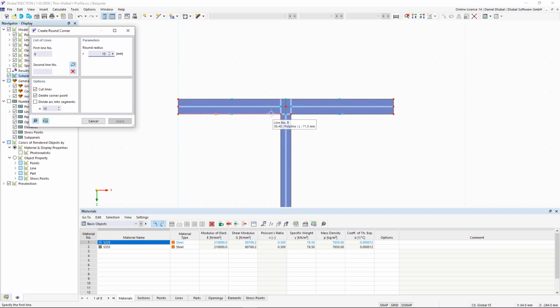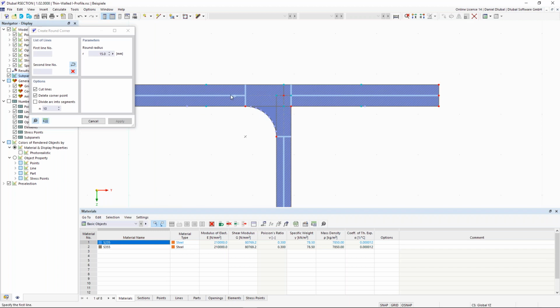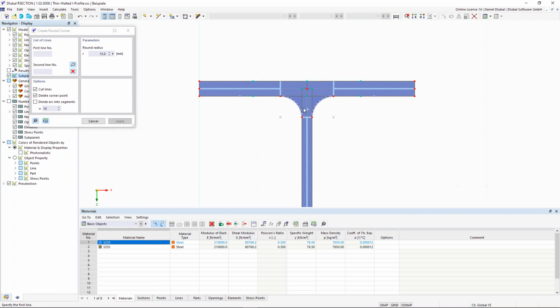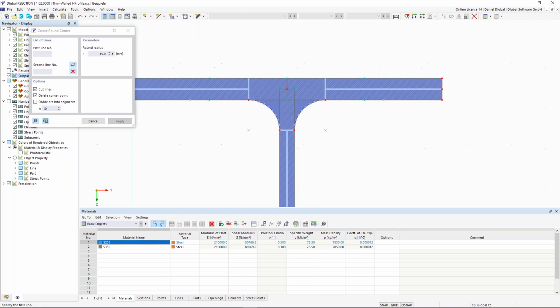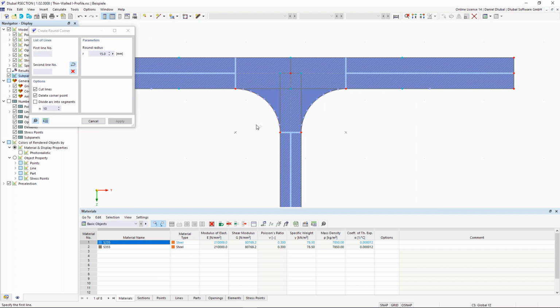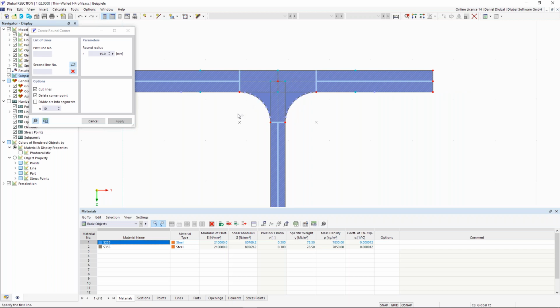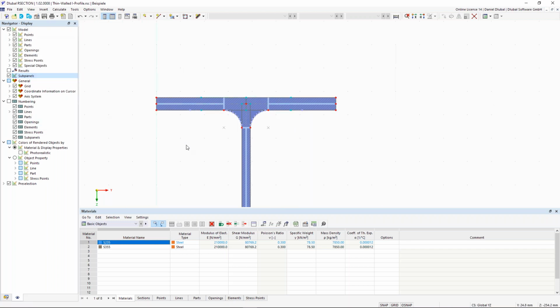I choose this line and this line, and then you can also see that the sub panels are fitted to the outer points of this radius. And let's do the same for the right side, and you can see how they change depending on the end of this radius, because this will also affect the cross-section classification. So right click, I will end this dialog.